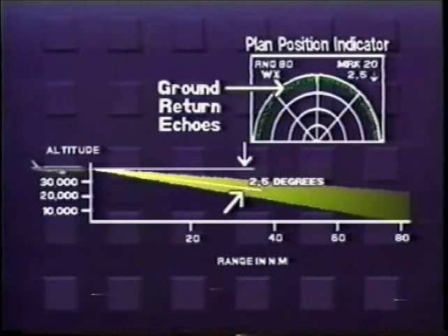Weather radars typically scan from one side to the other side in about 4 seconds, so be patient and make the tilt adjustment slowly. Continue to move the beam outward until only the outer edge of the displayed range contains ground returns. Let's say about 5% of the display. That's it. That's all that is necessary to adjust the radar for proper tilt management on any display range.